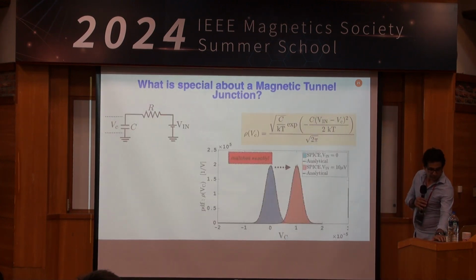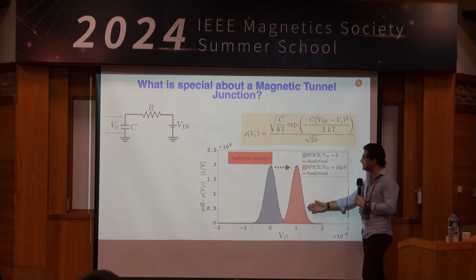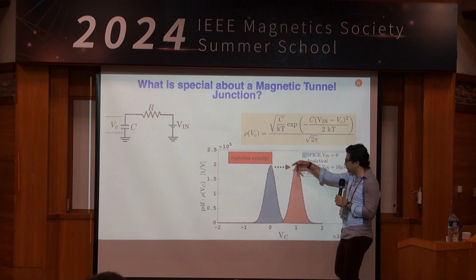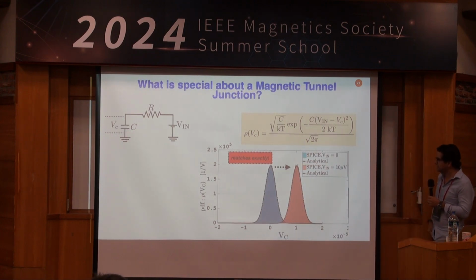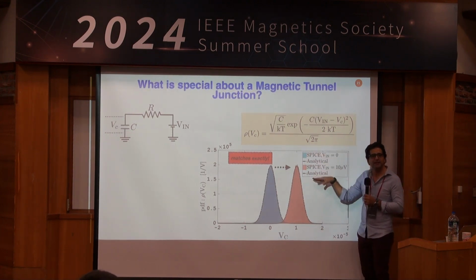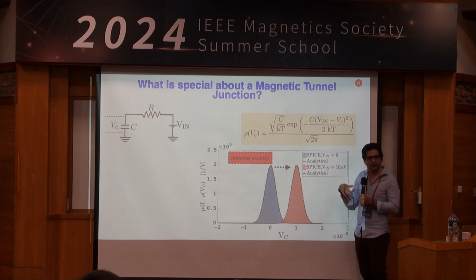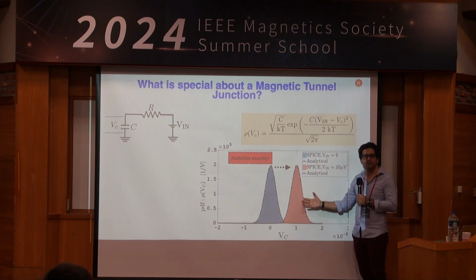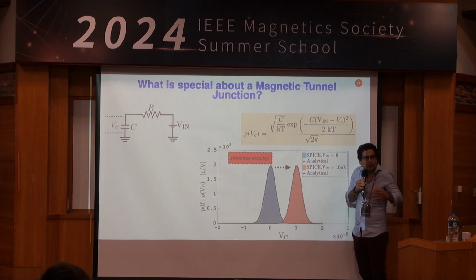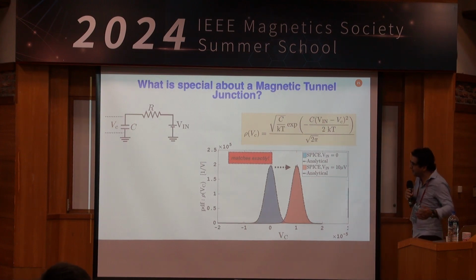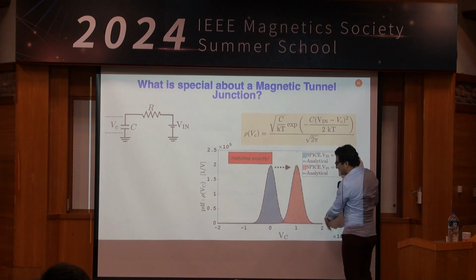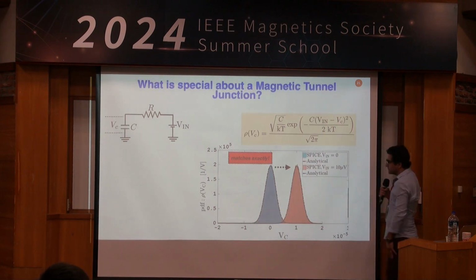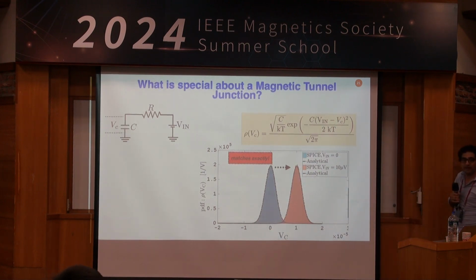So if you just plot that now, but for different V in, this is what you see. Okay, so a student did this for me, and they were very excited to get the same behavior from SPICE, HSPICE, the numerical circuit simulator. To me, the fact that SPICE matched this is testament to SPICE working, because the Boltzmann law can obviously not be incorrect, right? So SPICE gets the noise correctly. So this is a histogram of the voltages, okay, as a function of the probability distribution.